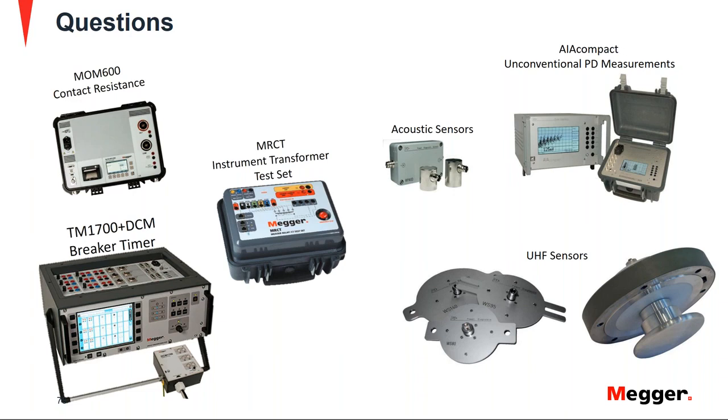So you can do either or. You can install window sensors on existing windows, or you can do flange sensors on flanges where you have epoxy as the insulating material there, or as we saw, maybe even you have the nameplate there. So these can be installed other places for sure, but unfortunately, if you're using these external UHF sensors, be it the flange sensor or the window sensor, obviously the window sensor is going to have to be attached to a window, and the flange sensor being the same.